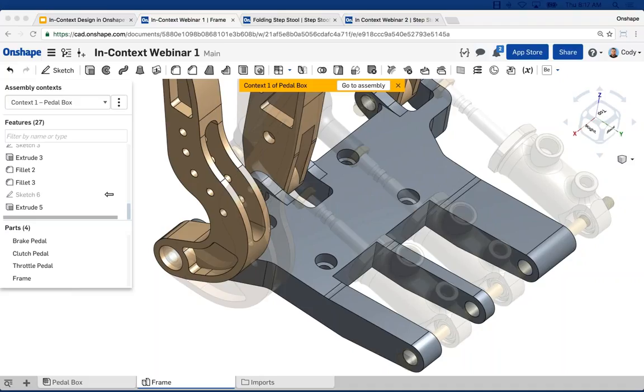Can I create parts within the context of the assembly on the fly? For instance, creating a blank assembly with 5 parts. Yes. I'm going to show you an example in a bit where you can create new parts within the context of the assembly, from scratch. So not editing an existing part, but creating a new one. And this also opens up potential for other things too, like layout sketches. A lot of users like the ability to have one sketch that drives many different parts, and you can do something like that at the assembly level now within context. So all kinds of very cool potential with this new capability.